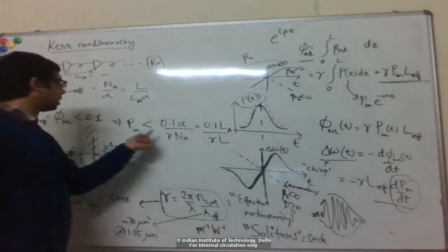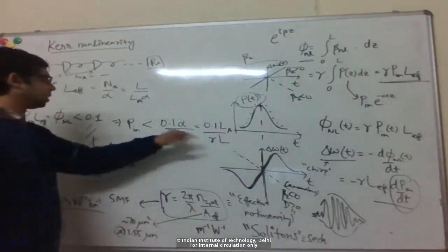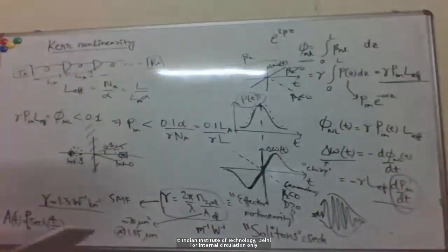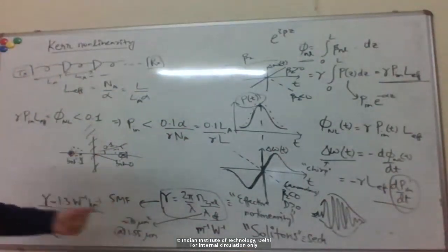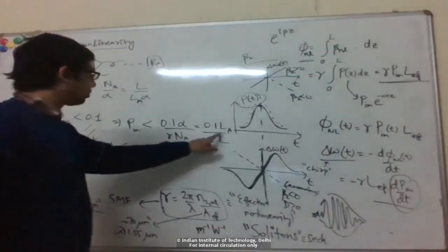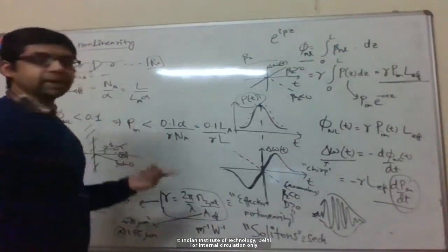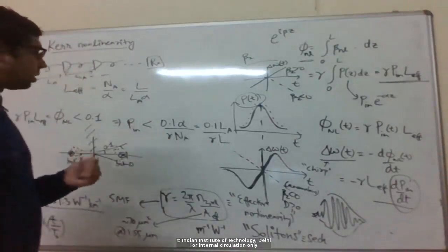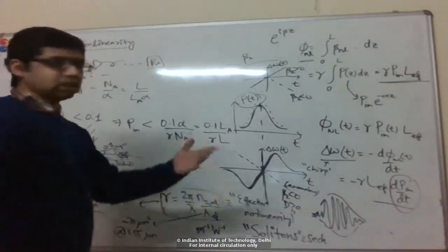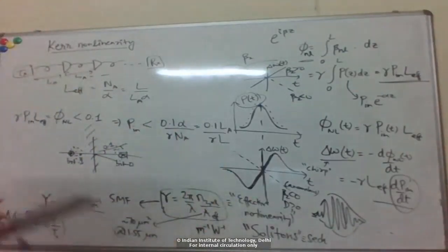Similarly here, this phase condition gives me a limit on the power I can set. So to maintain the same SNR and a low bit error rate, typically if I increase L, I want to increase P. But due to this nonlinear distortion, I'm actually not allowed to do that.